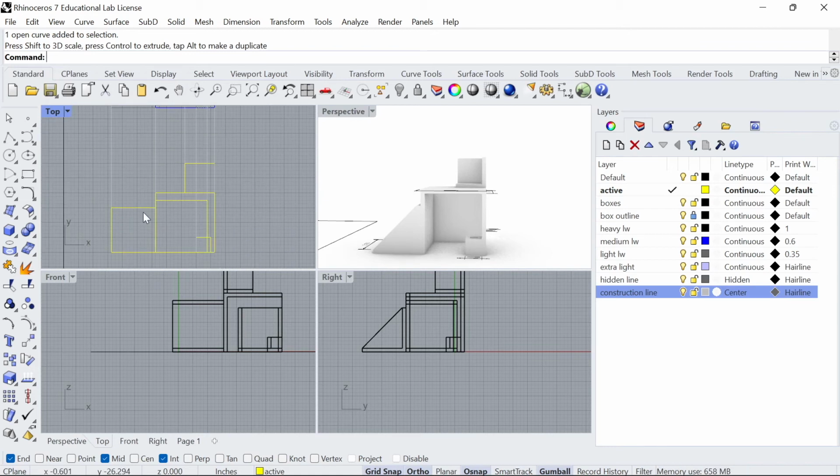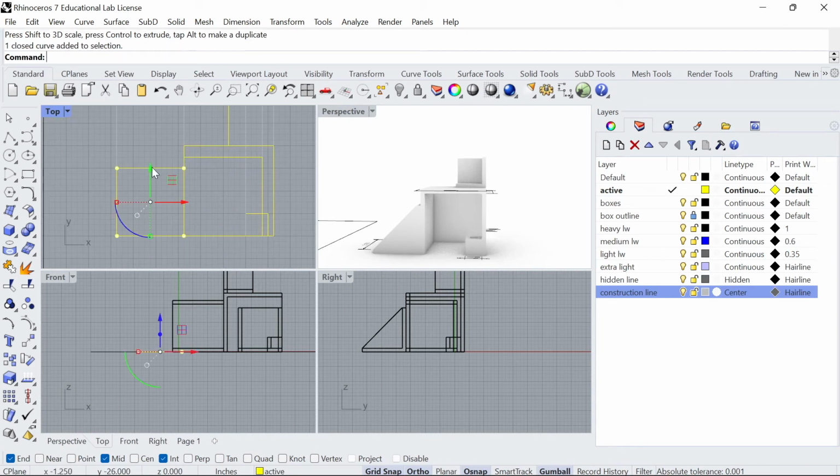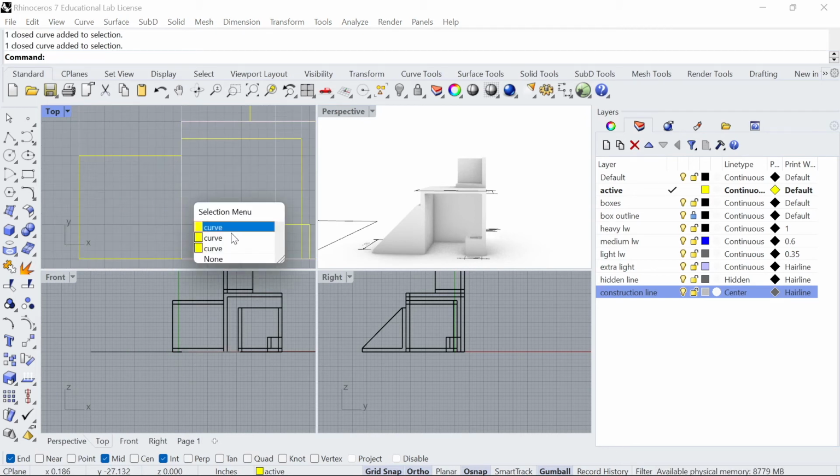We want to do the same process in this view, which is set up the line weights, add the thicknesses of the walls, and then determine what things are hidden and what are not hidden. Okay, so we do have an angled wall, so we'll just go ahead and start with this one. I'll go ahead and explode it. Okay, I'll go quicker this time. I'll select this line weight. So there's a lot of overlap. You kind of have to figure this out.